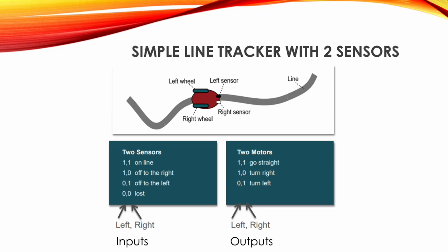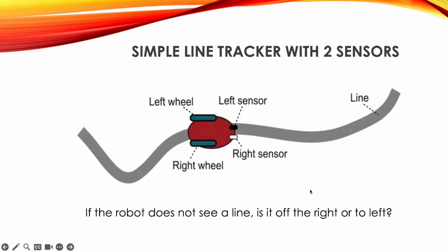And then we can control the motors, and again, the motor control is done by setting things to be high or low. Turns out that in order to turn right, we can essentially set the left wheel to be on while the right wheel is off, and if I want to turn left, I turn the right wheel on while the left wheel is off.